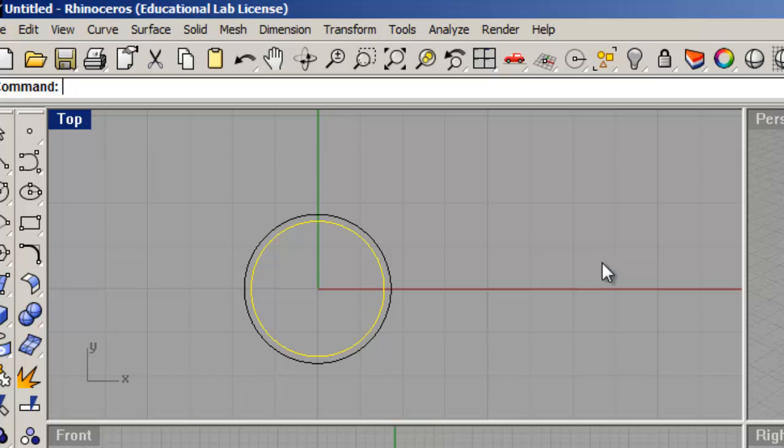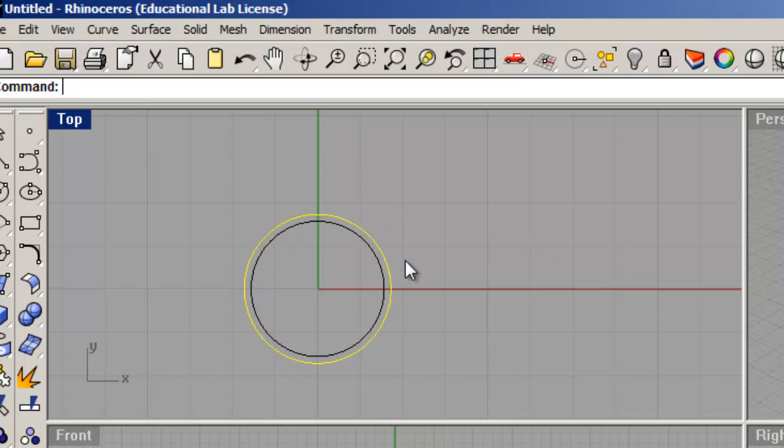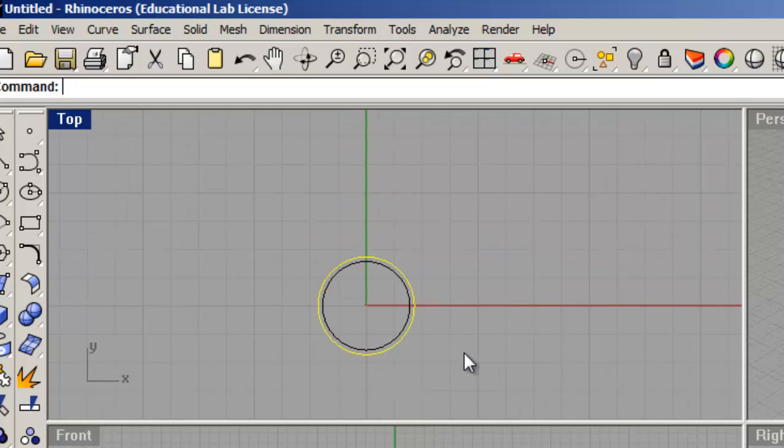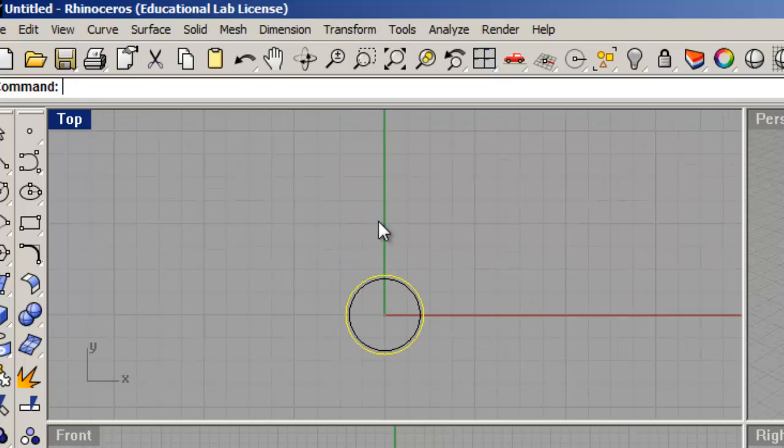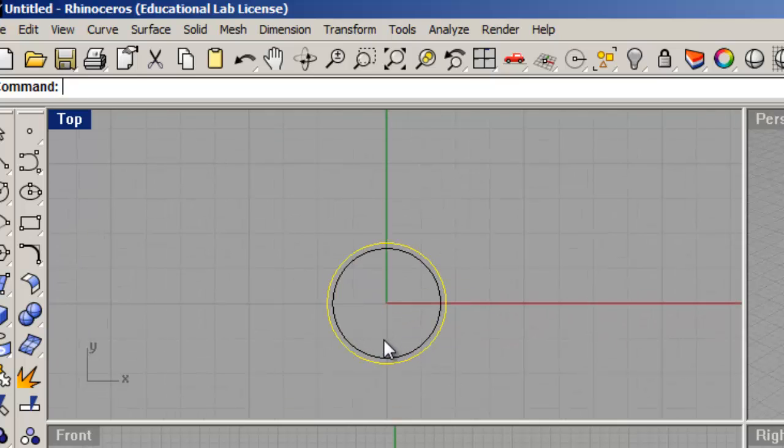Now, that was the recommended thickness. If you want to make it a little thicker, that might be a good idea just for your text. So you can always add a little bit more. You're not going to get in trouble for that. But I would say a minimum of 0.08 or maybe a little bit more, depending on how thick you want it. And you can sort of eye it. Remember, this is a square inch, one of these boxes here. Okay, we're going to keep everything in the center. You do not want to move these around. Okay, right now we have 2 curves.